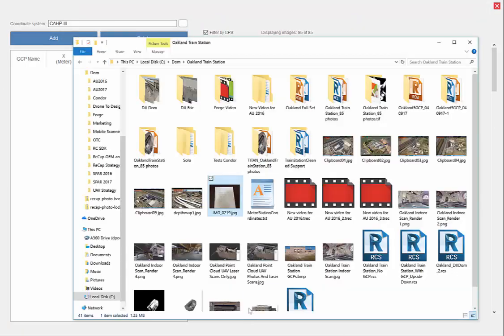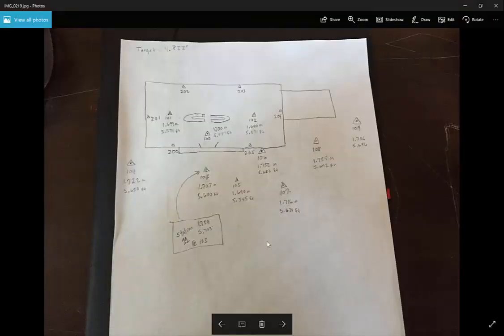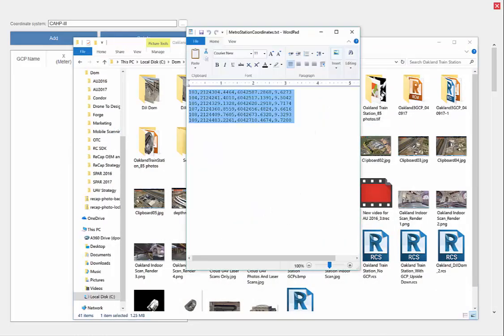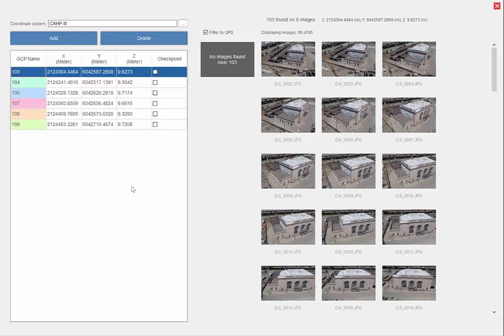So for this project, I know that the data has been collected along this map. And this data is now available in a text file that I see here. So what I will do, I will copy paste this data into my editor here, Control V here, to avoid any typing error, any typing mistake. This is only Control C, Control V, and only works with a text file, not an Excel sheet, for example.